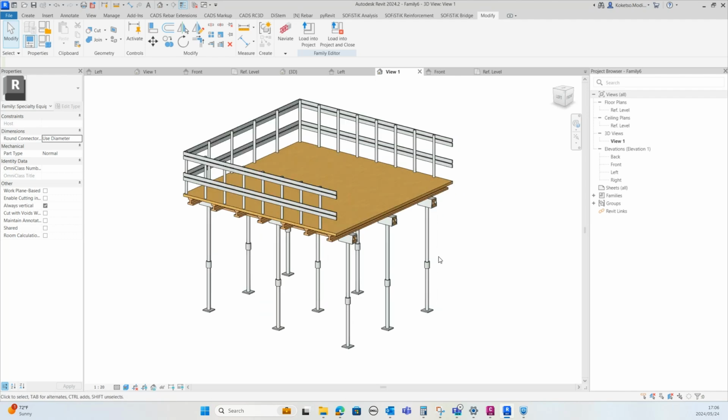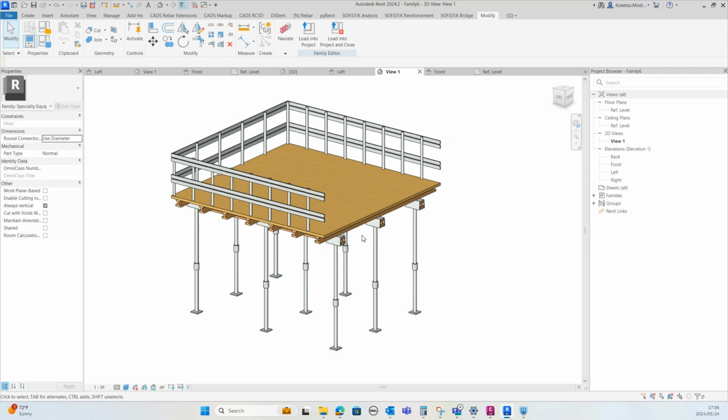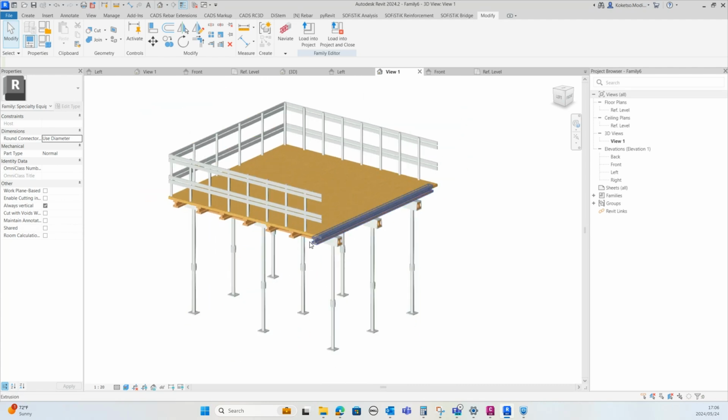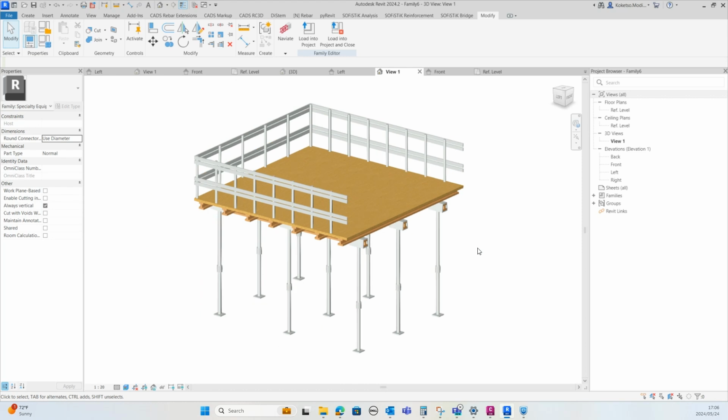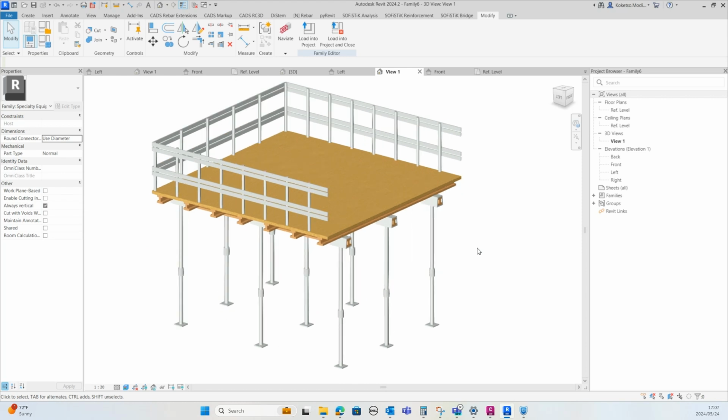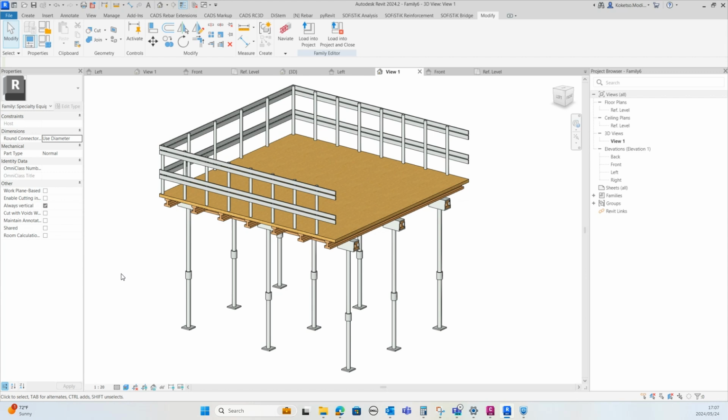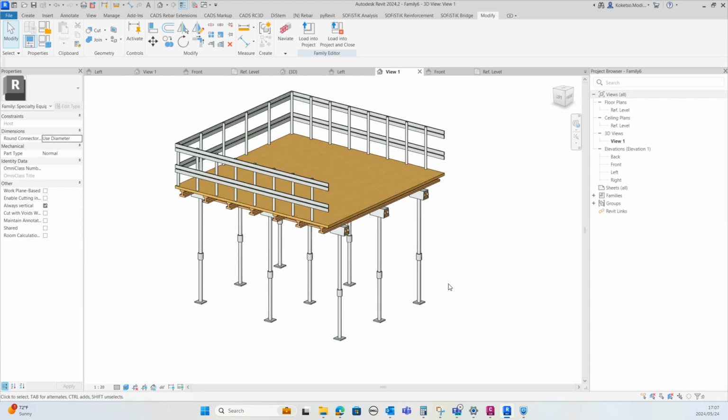Ideally, if you specialize in formwork and all those things, you want to quantify these materials and elements separately. So in order for you as a modeler to make it easier for those guys who are manufacturing this, you have to create a nested family, and then you're gonna have to check this shared parameter thing. This shared parameter allows you to separate the quantities of nested elements into a single family. So what do I mean by that? On the next tutorial, let me make an example.